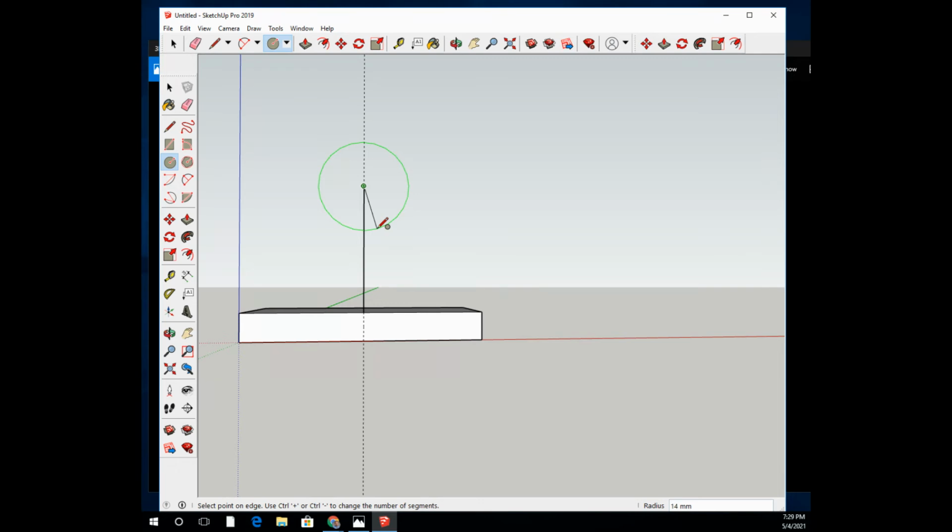Now the radius, not the diameter, we're looking at the radius right here. It's asking for the radius. The first arc was 15, so I type in 15. Go back to my center mark, drag away. The radius of my second arc was 23. So if I type in 23, that's going to post that. And we're approaching the end of my screencast ability, so we're going to stop there, and we'll pick up with a part 2 for this drawing.